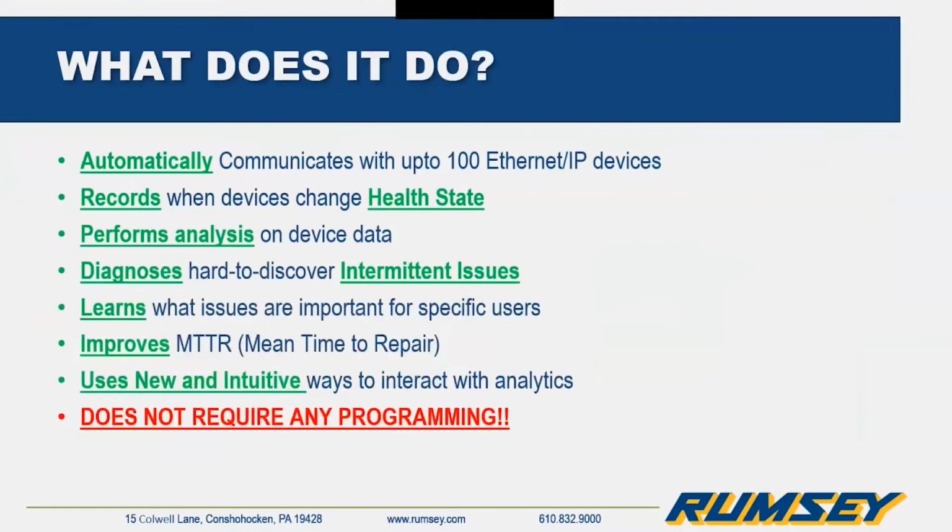Okay, so what does it do? What does this appliance do? Well, it does quite a bit of things actually. It automatically starts scanning the network to connect to any EtherNet/IP device out there. It records device health information and performs analytics using built-in device profiles. It diagnoses hard to discover issues such as duplex mismatches and can even display fault code information.